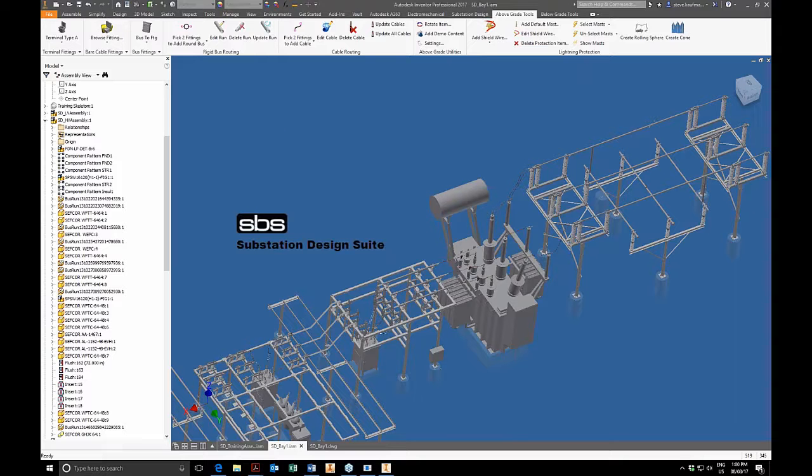Okay. When you put a bus bar with aerial conductors, a catenary is calculated, or is it approximation? The catenary is strictly based on the percent sag, and it's from that. It's whatever percent sag you place in there. So if it is an approximation, it's an accurate approximation, if you want to say that.